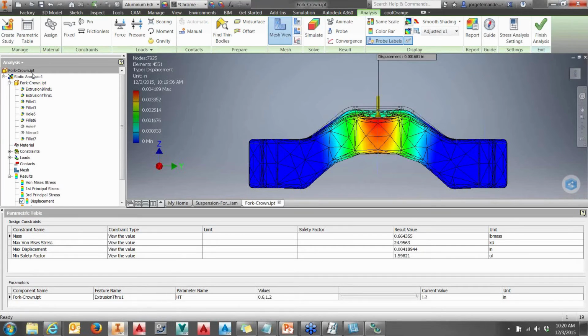And then, as I mentioned earlier, I can take the simulation and actually copy this study. I can create another one based off of these things, so I don't have to start all over again necessarily. One other quick thing also, since I'm looking at the browser here, if you did want to apply a local mesh control, this is where you would do that too. You would right-click, hit local mesh control, and we can do that to specific faces on here. So just a little useful information. Hopefully this gave you a little introduction to static stress analysis.